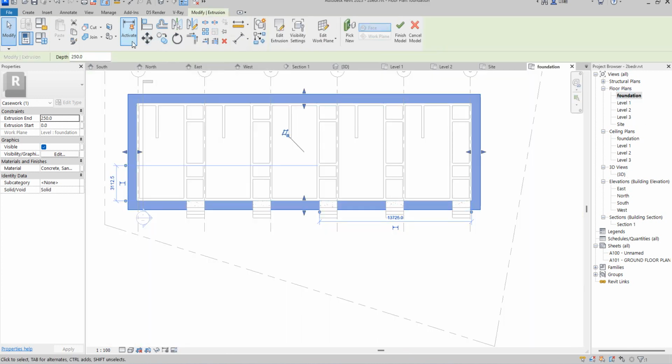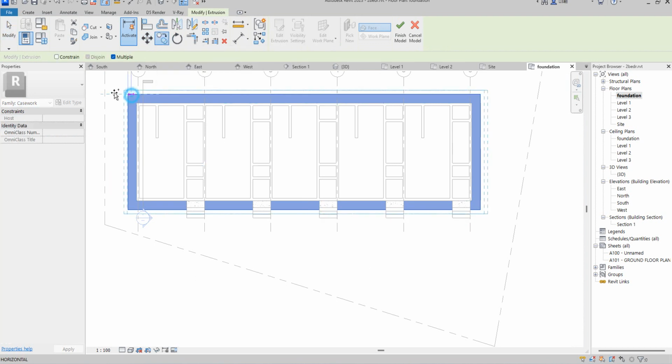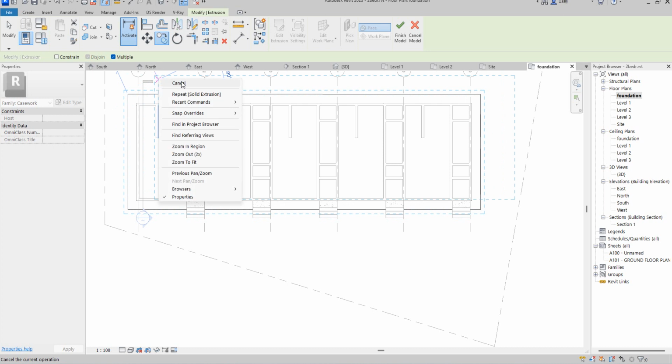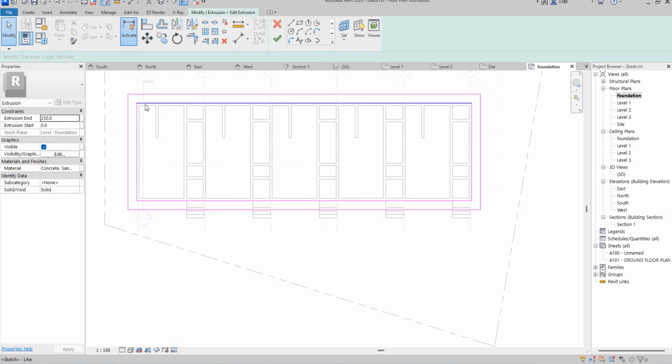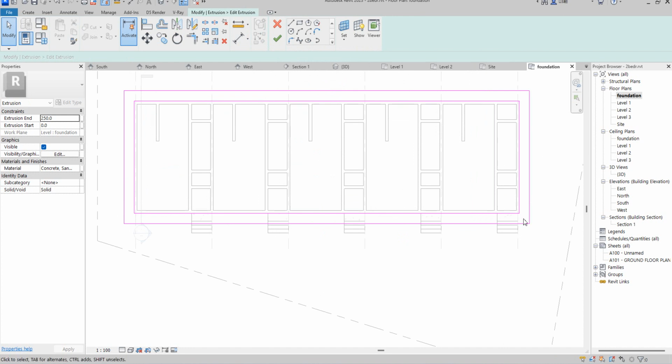So what I'm going to do is that I will select, just copy and press 1. So it's going to copy almost the same instance. So we say edit in place. So what we do, we delete all the internal references of this. Then you say select here and you say offset. So offset here, let's just have 120.